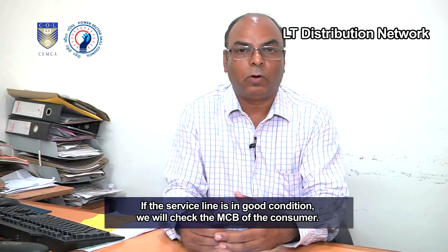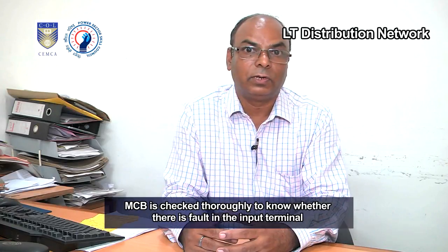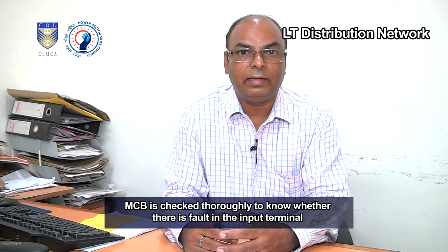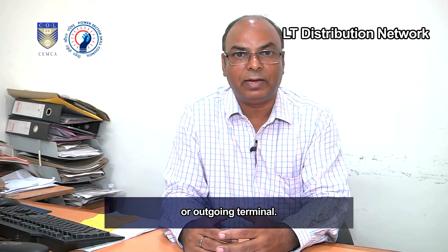If the service line is in good condition, we will check the MCB of the consumer. MCB is checked thoroughly to know whether there is fault in the input terminal or outgoing terminal.